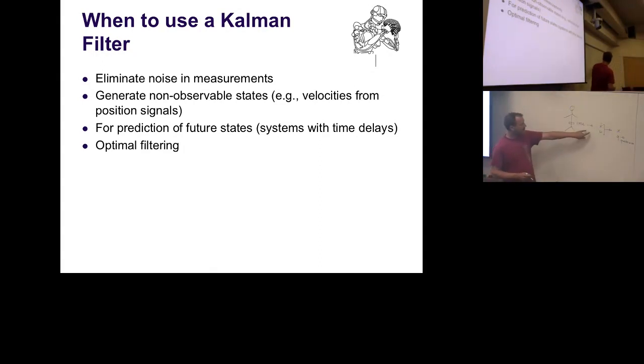Cool. So this is a typical state estimation problem where you get some signals which are not directly what you want. And out of those, you have to create the correct signals. And that's actually non-trivial in this particular case. Because you can already imagine that just from knowing how fast you move or how fast you're rotating, you cannot figure out where you are properly. And actually figuring out the orientation of your body is not that trivial either. So this is a more advanced example of Kalman filtering where you uncover unknown states from some measurements. And this is still research.